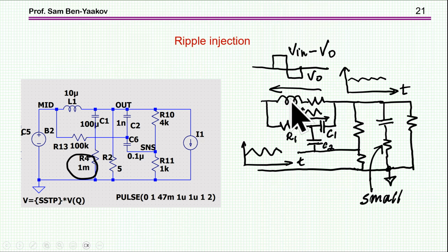And as you might know, this is actually the idea used to measure the inductor current without an additional sensor, just relying on the inductor and the internal resistance. Okay, this is a well-known technique. Here, we are using it to generate just the ripple. We're interested in the ripple.